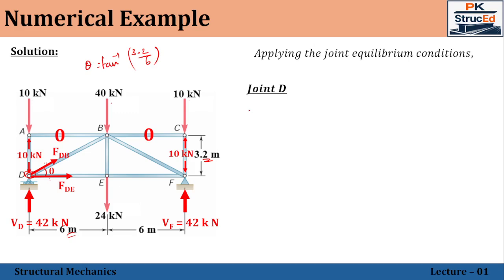So that comes around 28.07 degrees. So we can substitute this value anywhere, wherever it is required. Now, taking the joint forces separately, we'll have this theta available. Right. So substituting the equilibrium equations, we can see Fy. I'm starting with the vertical force equilibrium.